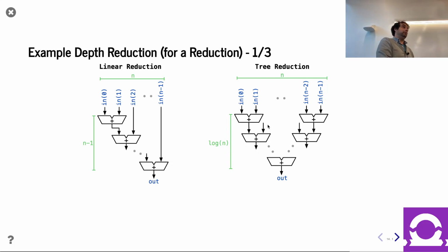Yeah, that's a great counterpoint, and I'll try to best convey this for the recording. I'm happy to have this conversation. First off, the point was correct about mathematically how many bits we need to not lose anything to overflow. The answer is yes: k plus log n is sufficient. So the tree with the growing adders will not lose data. The fact that the other one is doing not just k plus log n but k plus n minus 1 is overkill.